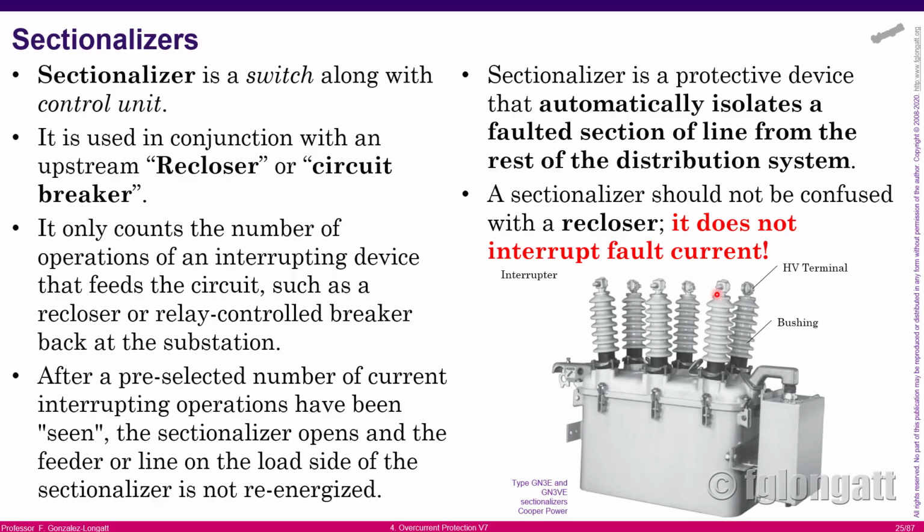Now I will show you a device that is the sectionalizer. The sectionalizer is mainly a switch. It's not a circuit breaker, okay? You must be careful. A switch is not able to interrupt fault currents, okay? However, this sectionalizer comes with a control unit similar to the recloser, okay? Sectionalizers are used working together with the reclosers, okay? Or they can work together with a classical circuit breaker with an overcurrent relay, okay?